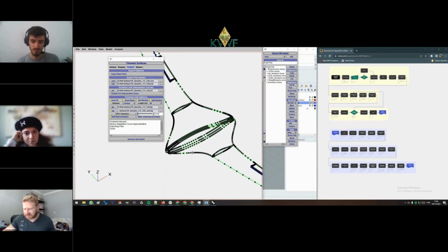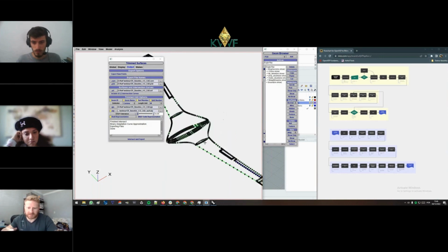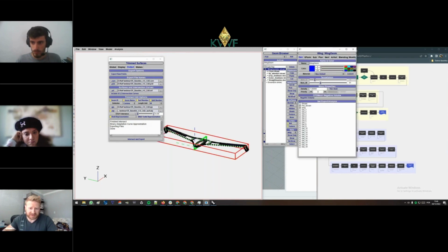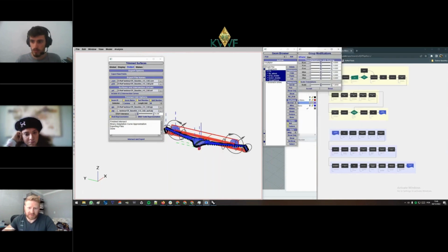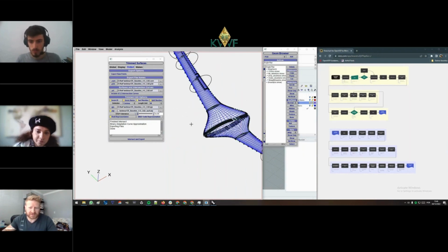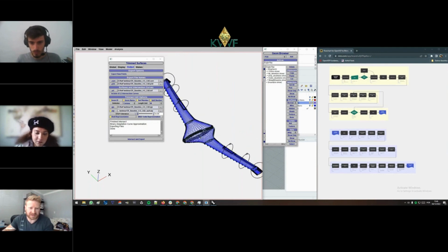Yeah, with the trim surfaces in particular, it's using the underlying Bezier curves. So the surface representation that you see in OpenVSP with, say, your num-U or num-W settings shouldn't have any effect whatsoever on what comes out as CAD. So num-W is 41, could be 101, it could be 17. You'll still get the same surface from trim surfaces because it's using the Bezier curves.